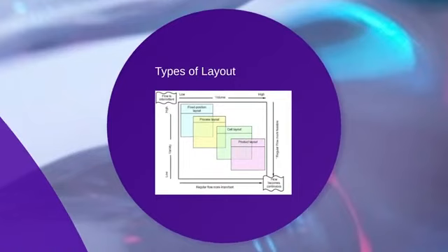We have different types of layout in the facility layout, but we will state the four main types. The fixed position layout is where the components are fixed, but tools or machines are moving around these components. This is suitable for just several orders, bulky products, and variable demand. The next is the process layout, where the equipment performing common functions is grouped together. This is suitable for processes having continuous change of product and variable demand also. The cellular layout involves grouping into families based on common machining requirements, which is basically placing the machines in a loop.